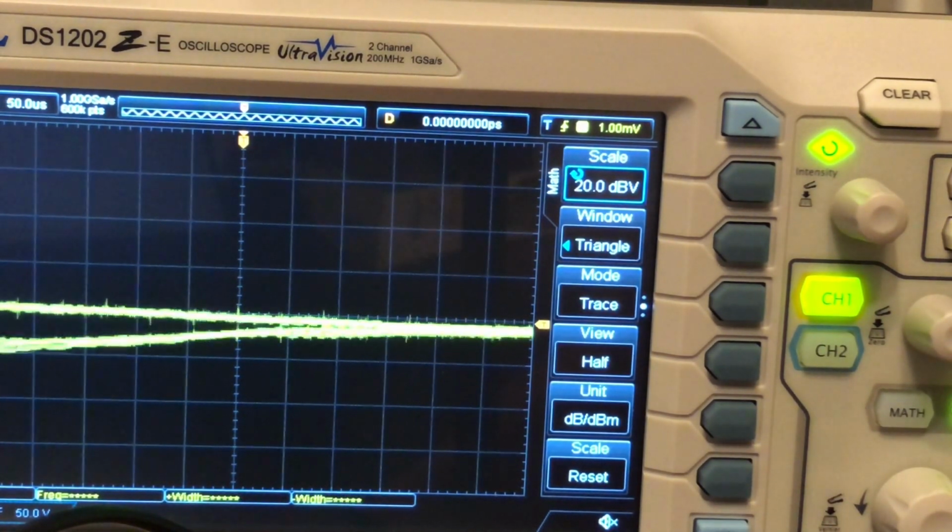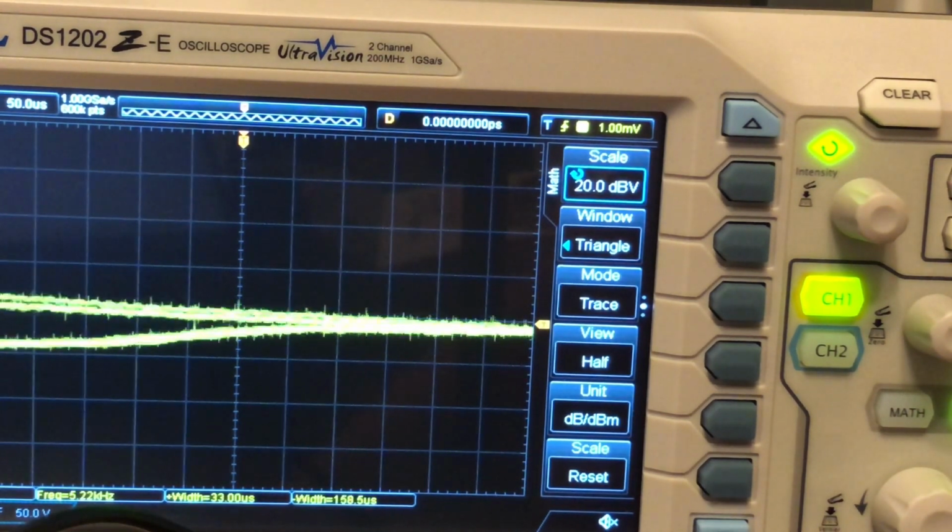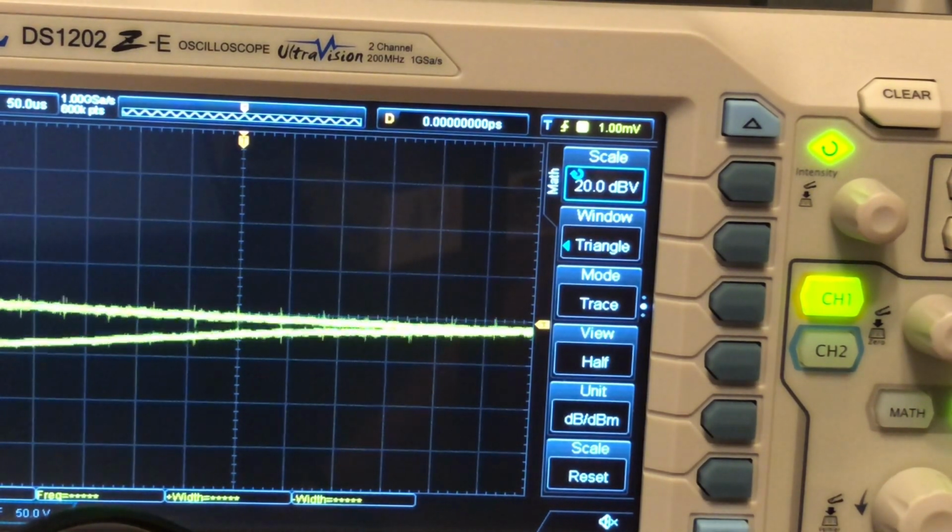Memory is the data source of the FFT operation, is the data of the waveform in the memory. And the length is up to 16,384 points. When the memory depth doesn't exceed 16,384 points, all the data is used for FFT operation. Otherwise, the instrument will read the data of 16,384 points according to the trigger position.